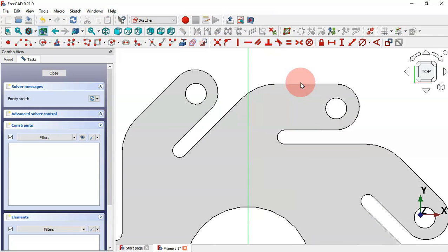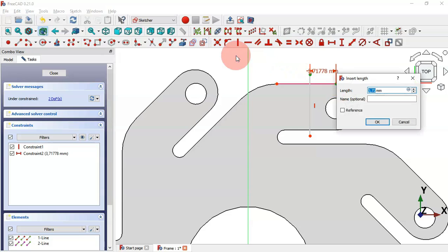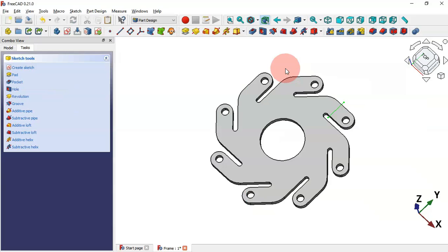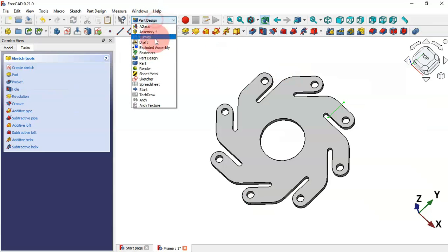Okay, zoom in and select the external geometry tool, extract this edge here, select the line tool and draw this vertical line, select the horizontal distance tool, and now these 2 points here, set a distance of 5.95 millimeters, and now escape 2 times to leave the sketch